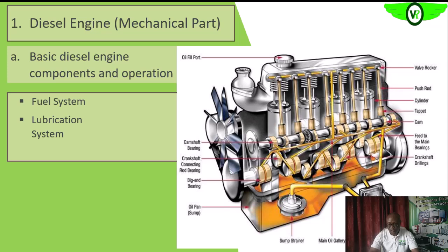Remember, we said those joints, since we have metal to metal contact on those joints, we really need to ensure that they are properly lubricated so as to reduce the friction, okay, at those points on the crankshaft, even on the camshaft, and also on the piston within the cylinder itself. You know, as it's moving up and down, it is scraping on the cylinder wall. Okay, so we actually need to reduce the wear. We need to lubricate that area so as to aid the to and fro movement of the piston. So here we have the lubrication system from the oil sump.